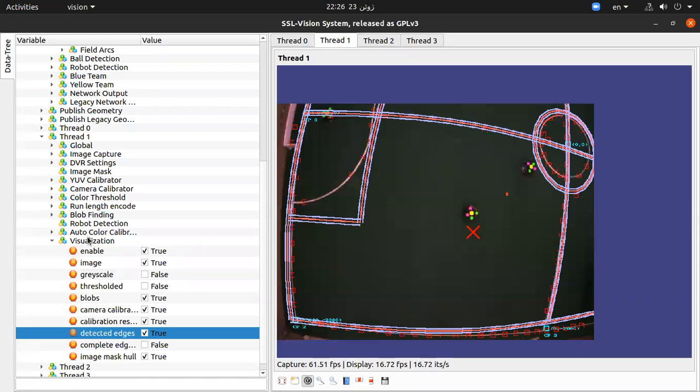So the basic idea is you have the scenario and you have these absolute positions, and also the distances between all the robots, and this should not change. You should not scale this up, because then it's completely different and not comparable to others. So that's why you have to configure your SSL Vision for the specified dimensions. You will only play on part of the field, and you will probably need to align the smaller part to your goal, because your goal is fixed. Everything else can be adjusted.